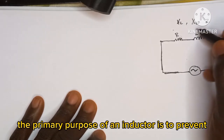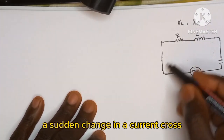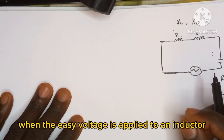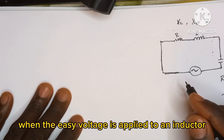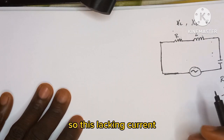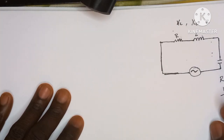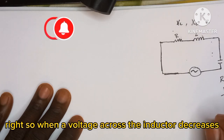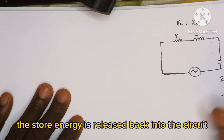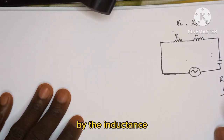As for this inductor, the primary purpose of an inductor is to prevent the sudden change in the current across the circuit. Basically, when the AC voltage is applied to an inductor, the current through it lags behind the voltage by 90 degrees. So this lagging current creates a magnetic field around the inductor, right? So when the voltage across the inductor decreases, the stored energy is released back into the circuit by the inductance.